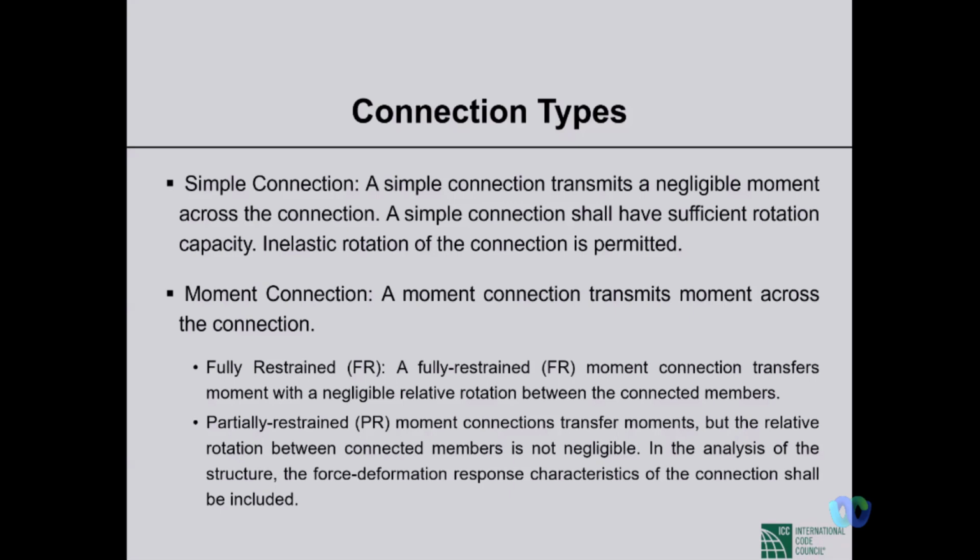In this case, if we plot the moment curvature relation, that gives a non-linearity into the system. So if we use partially restrained connection, and if we want to take that into account in our analysis, in that case, we have to go for nonlinear analysis.